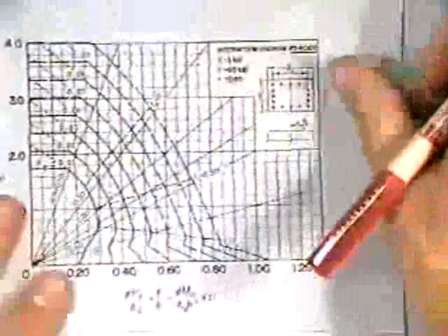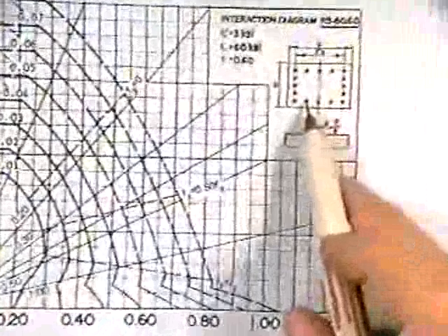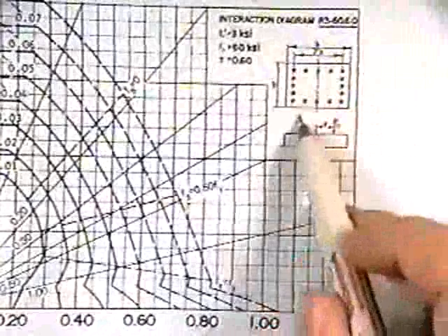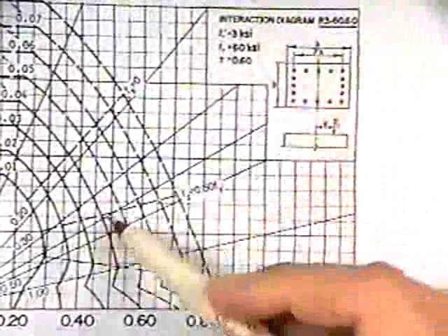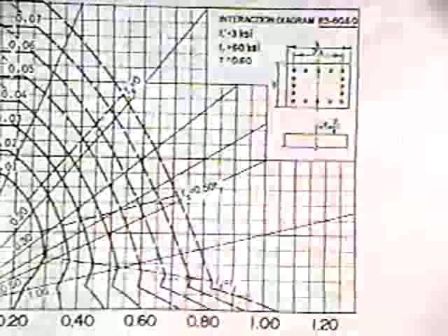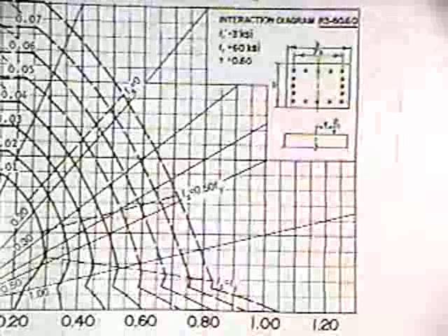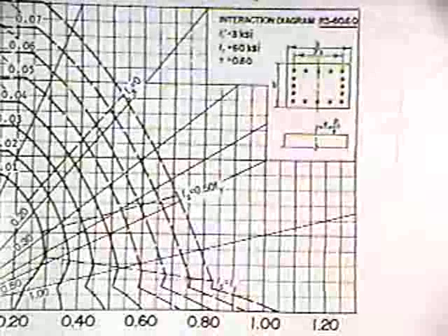Remember, your steel goes into tension, and the right side goes into compression. Now there are other charts for when the steel is more uniformly distributed around the column. I think that's on your 3rd and 4th sheets. If you want to place steel all the way around the column, so this has bending in both directions, you would do it something like this. Use these flow charts and space the steel uniformly around your column. That's actually for bending just about the one axis shown, but you pick up some more strength because of the other bars.